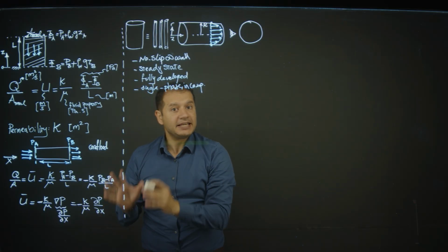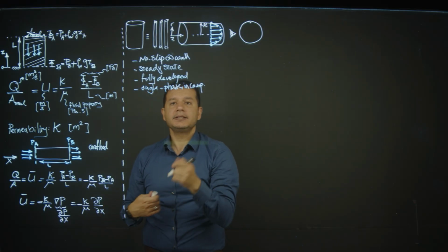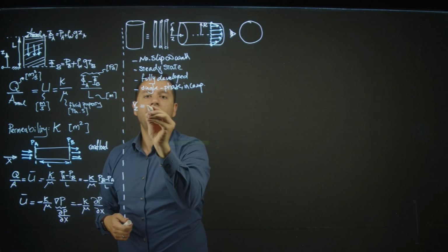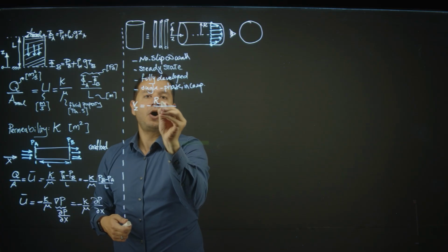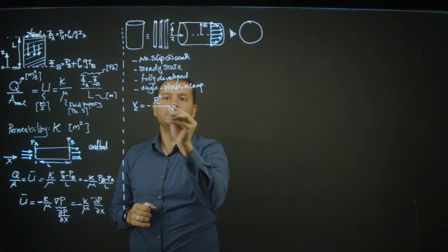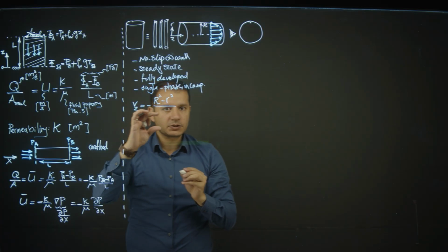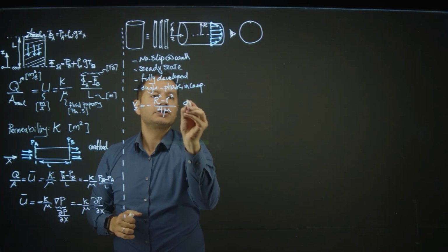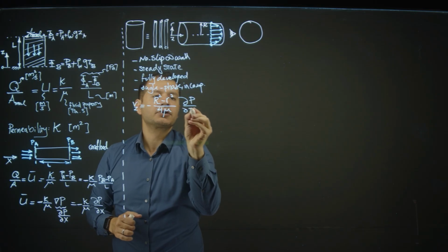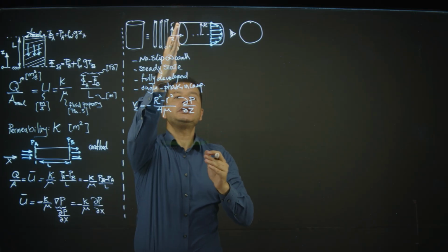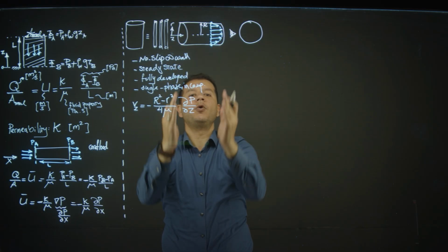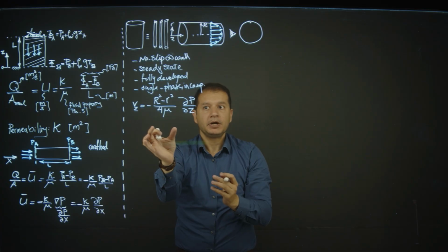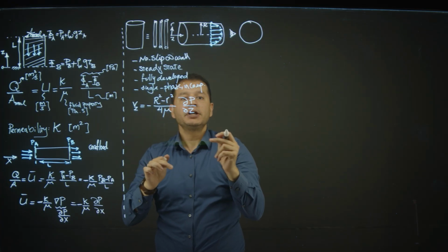The formula that we get from the Stokes analysis is that velocity across the Z-axis will be minus (R² − r²) over 4μ, where capital R is the radius of the tube and small r is the radial position, times the gradient of pressure across the Z-axis, which is dP/dz, (P_B − P_A) over L, the distance. That's the V_z. Now, this is the velocity of the water, and we can check it.